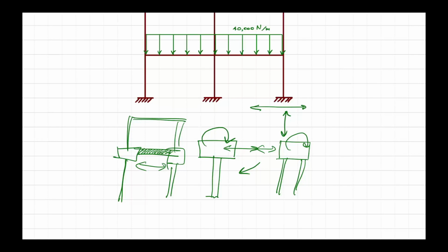Okay? So this is extremely important, and this is a part where many times the collapse or failure is caused by inconsistency between the structural analysis model, especially the condition like hinge at the support, versus the real construction. You don't want moment here, but you put a fixed member there that restrains the moment, then you end up with trouble. Or sometimes you want that thing to resist the moment, but you release the reinforcement, then you get into trouble, right? Make sure that everything is consistent.